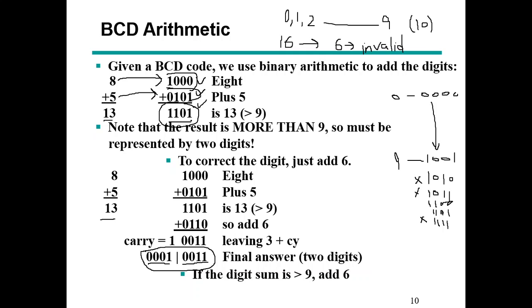ठीक है, तो फिर कैसे इनको करेक्ट किया जाए? तो मैंने आपसे कहा था ना ये 6 का नंबर आप याद रखें. So there are 6 invalid codes. So if you add 6 to this sum, तो आप वो invalid codes को फलांग जाएंगे. आप उन invalid कोड को उनसे जंप लगा लेंगे. ठीक है, तो यू वुड अवॉइड दोज इनवैलिड कोड्स।